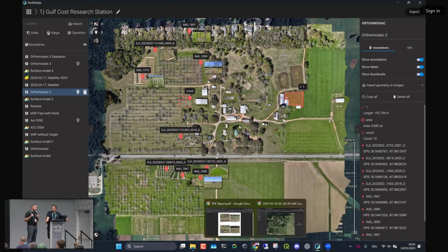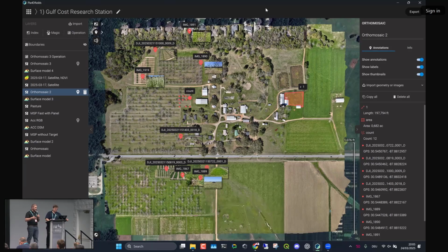Yeah. So the question is, if I understand you right, you're asking for offset correction or calibration or ground control. XAG has this, I think DJI has it too. You could use their base station. You set it on a known point and you say, this is where I am. You can do this through the software. You'd have to export a point in here. It's rather long, and I don't want to give a lot of explanation on this because it's fairly detailed. But yes, you would be able to do this.